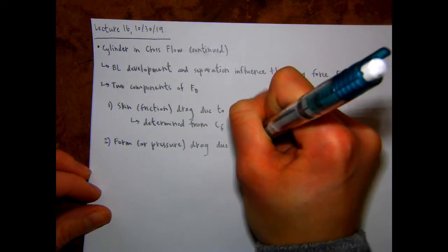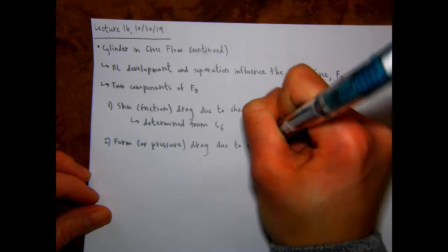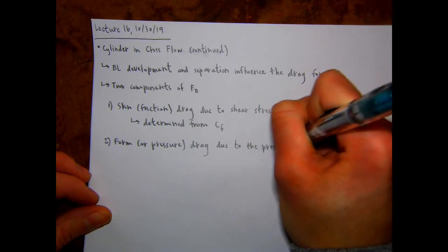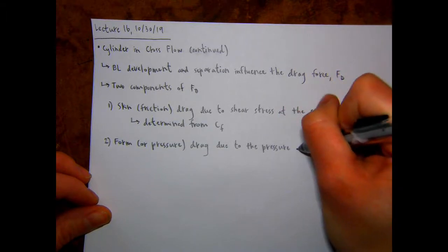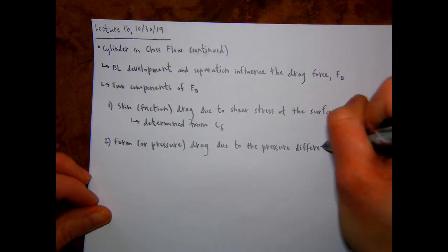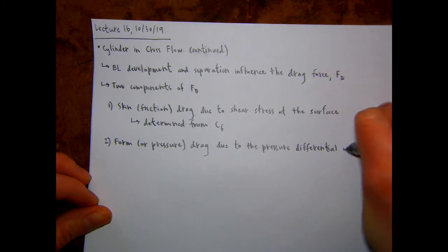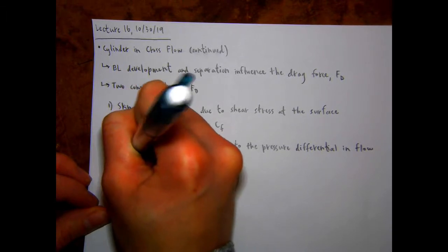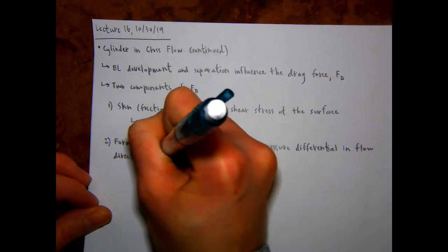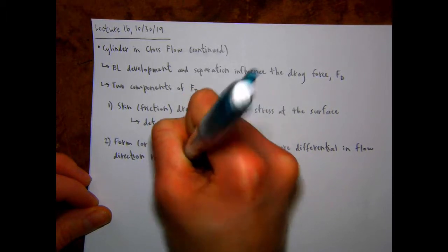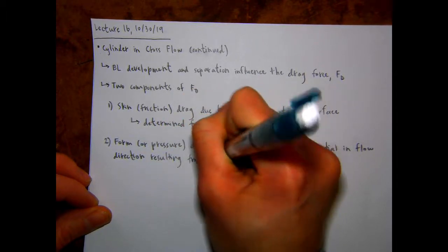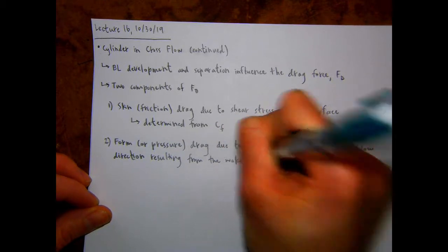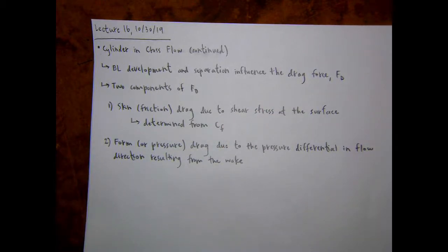And it is due to the pressure differential in the flow direction resulting from the wake. So we have a higher pressure upstream of the cylinder and a lower pressure downstream of the cylinder in the wake.